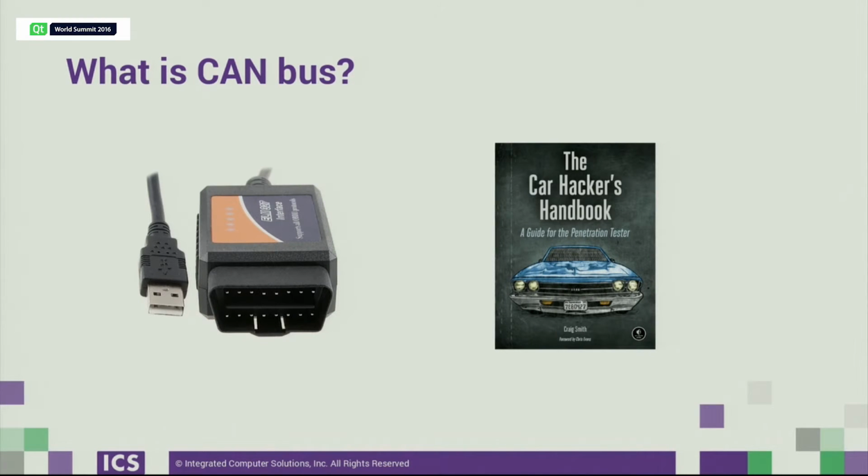So if you want, you can actually look at CAN bus messages in your car. There's a number of low-cost devices or interfaces that can plug into this OBD-II connector and interface that into a USB bus or serial or Bluetooth, and let you see what's happening on the CAN bus and even inject CAN bus messages.